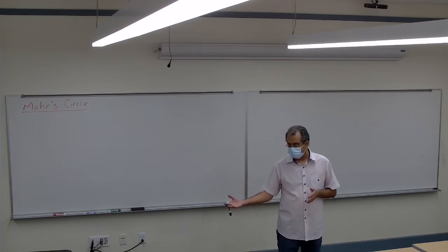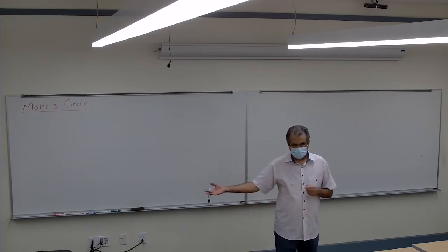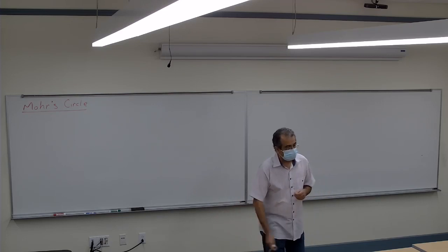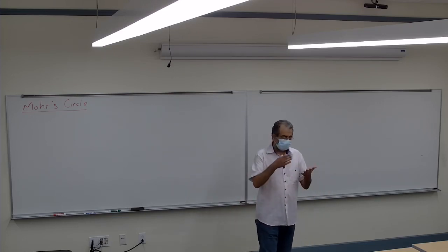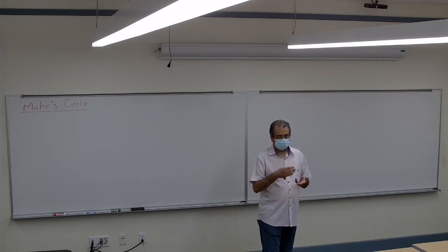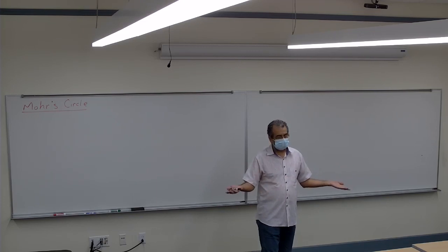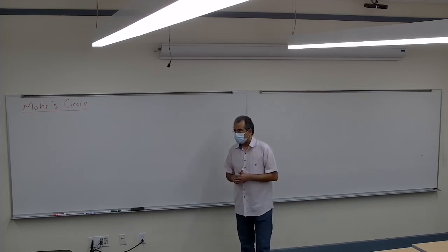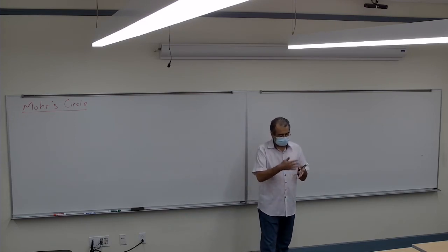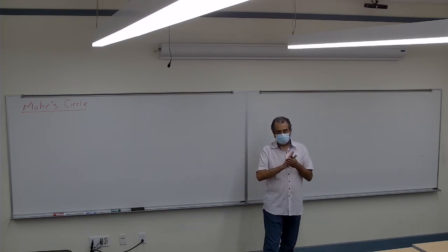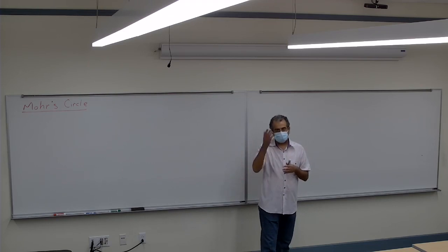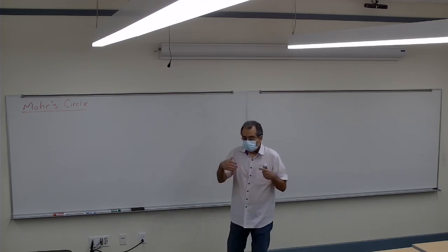A very quick review of what we talked about last time: in all the axial load, torsion, bending, and shear, we come up with two types of stress. It's either normal stress or shear stress. And what we calculate in any of these four loadings is going to be either parallel to the x or parallel to the y-axis. That's all we have.